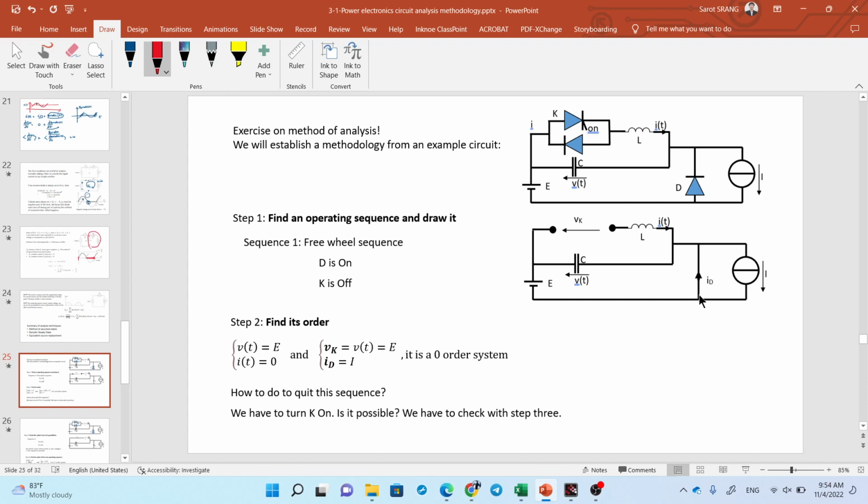Okay. Well, first let me explain the notation and the symbol here. This one is the symbol of a current source. Current source means you have a device here that controls the circuit in such a way that the current that flows from here to here is always I, capital I. No matter what you do with the circuit at this part, it tries to generate current I.